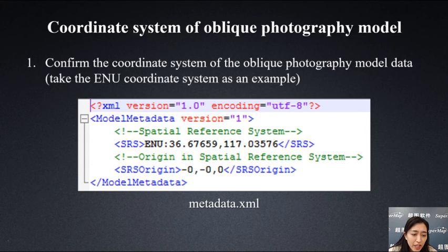And for the ENU, what is the ENU projection coordinate system? It is a station center coordinate system, with the station as the origin. The 3 coordinate axes point to the east, north, and sky directions respectively. The station center coordinate system is also called the east-north-up system. It means ENU coordinate system, and it is